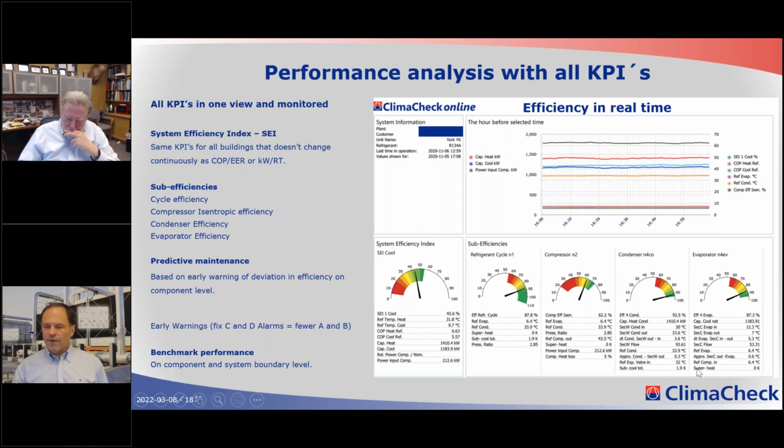Then, of course, all the values that people use to evaluate an air conditioning refrigeration system to make it a professional maintenance control would, of course, include subcool, superheat, approaches and so on, and delta T's and flows. All these are, of course, also established and can be monitored.